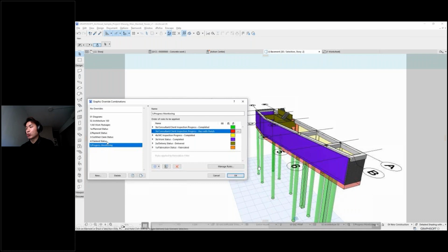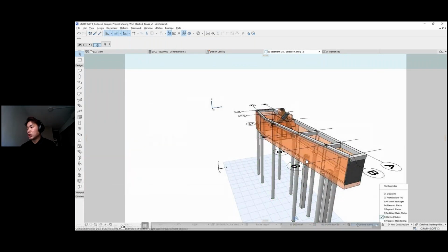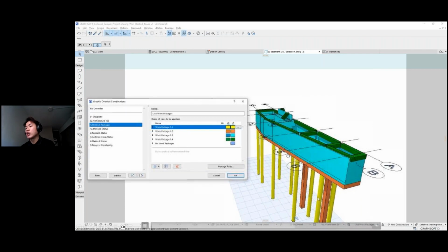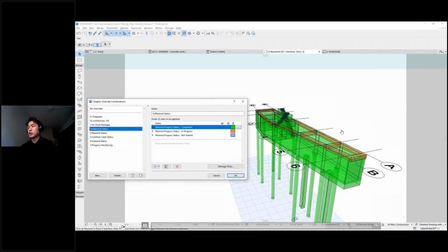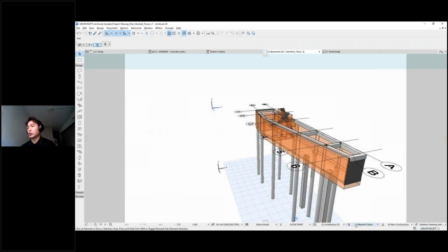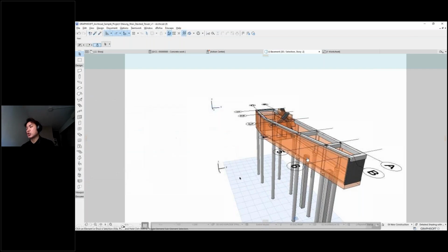Just now I also showed you BIMx, and using BIMx itself, you can see this. You can also see the claim status and also the work packages, meaning which element belongs to which work package. After that, you can save the view of each of these graphic overrides, and then place it on a layout to easily see the status and also the claim progress, and so on and so forth. You can see these are all the payment statuses, at which stage, and how much is being paid.